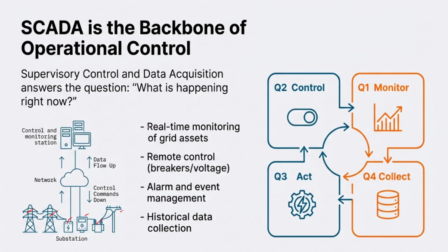Yeah, so it's all about the real time monitoring. Every 24 by 7, and we are able to set the timings. It could be every 1 minute interval, or 5 minute, or 10 minute intervals. These intervals we can set in the SCADA system for the real time grid asset monitoring. When I say grid asset, it could be a control unit, it could be transformer monitoring, and so on.